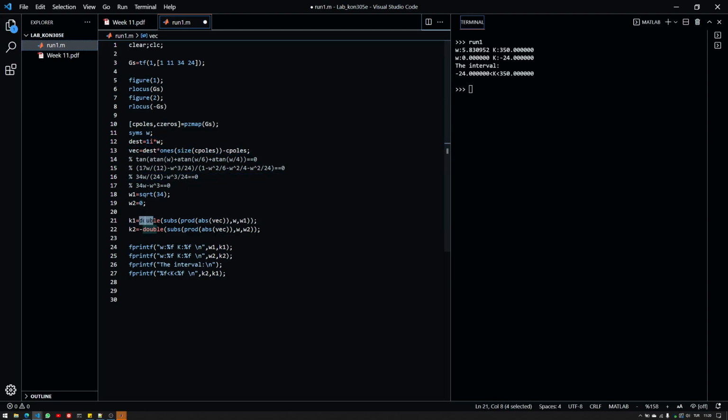That did correspond to our gain value. But here we did substitute the omega 1 value for the gain that is needed for omega 1 assignment, and then omega 2 for k2. But we did need to check out the root locus plot in order to determine which one was positive, which one was negative. And once we've done that, the information was basically computed.